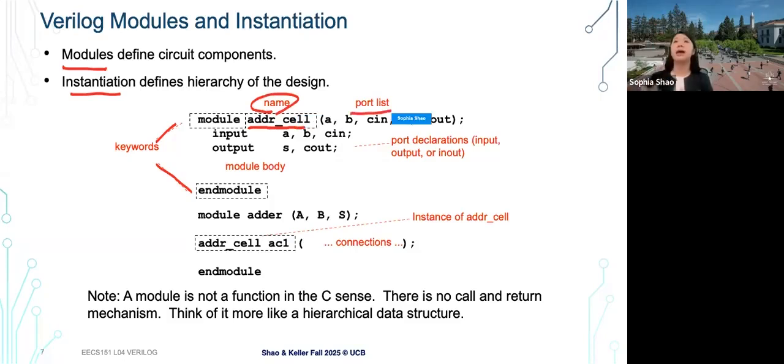And we mentioned earlier, any kind of circuit has a bunch of inputs and produces a bunch of outputs. We'll talk about combinational and sequential logic later, but here you also want to declare what your inputs and outputs are, or what your ports are. So that's a port list. Here you can be more explicit: here's my input, here is my output. Then in your module body, we'll talk about how you describe this particular adder cell. But that's a very common structure.